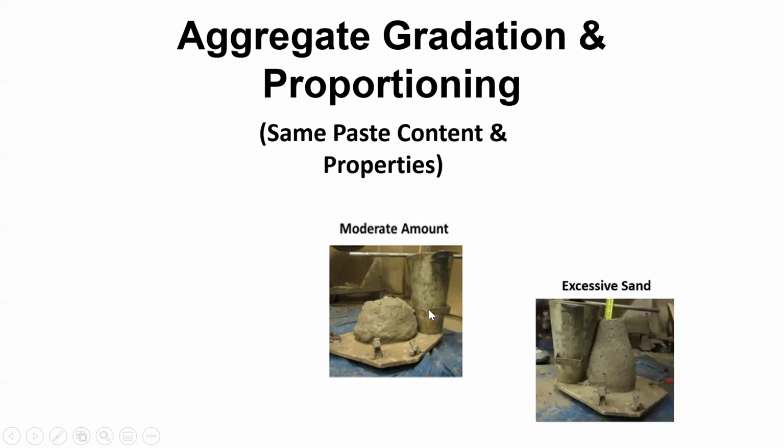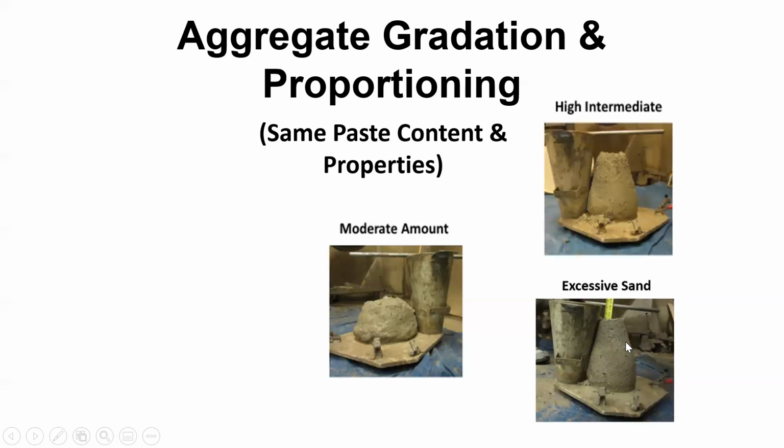And so what I did was I took out some rock and put in a lot of sand. If you have too much sand, then you're going to get a nice stiff mix that's not only stiff, but it's sticky, and it'll stick to everything. So it went from being a 5-inch slump to I think it's down here at like a 2-inch slump. So again, the only thing I did, they're completely different workabilities. This is great for floor slabs. This is not. You may not even want to pave with this, even though it is a 2-inch slump, because it's so sticky.